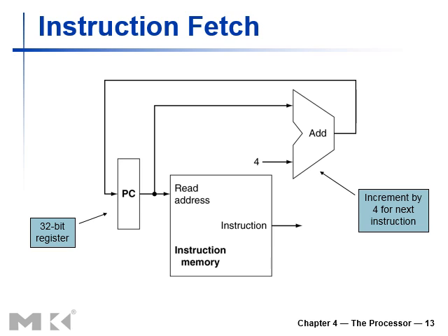The first element is a program counter, that is simply a counter that provides the addresses of the instruction to be fetched. The compartment itself from where we have to fetch the instruction, and that is instruction memory, and the adder that basically generates the next instruction address. And we have to increment this by 4.